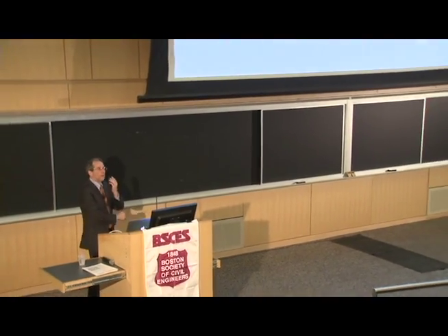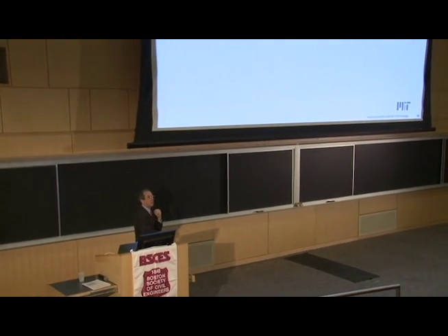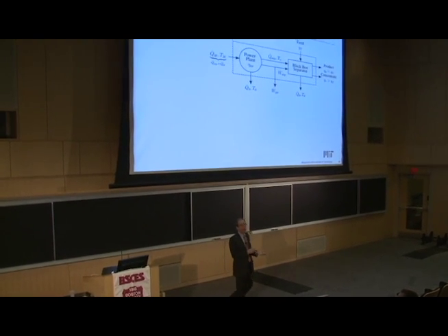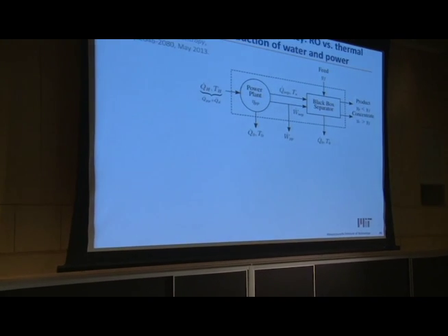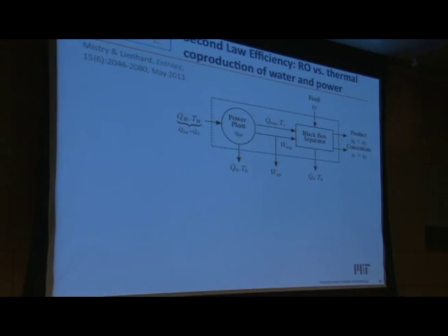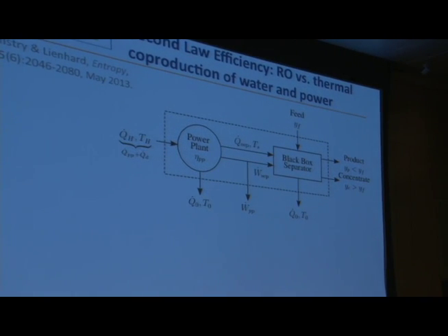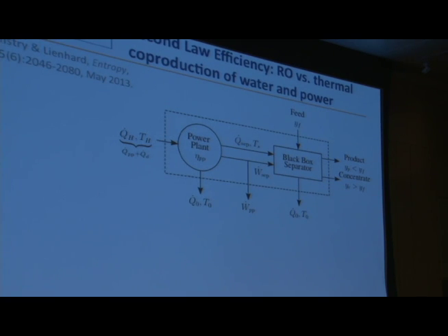The other thing you might wonder about as you think about this efficiency, I gave you efficiency numbers for energy going right into the plant, the electricity going into the reverse osmosis plant, or the heat going into the thermal desalination plant. But these things are also done as co-production, where you're taking primary energy, the coal you burn, well, let's hope you're not burning coal, the clean fuel that you're burning in the power plant, natural gas, shall we say, and you're burning that, and then you're using it to produce electricity and perhaps some steam blowdown. And you could take the steam blowdown and you could drive the thermal desalination plant, or just not have the thermal desalination plant and use some of your electricity to make water. You have choices to make here.